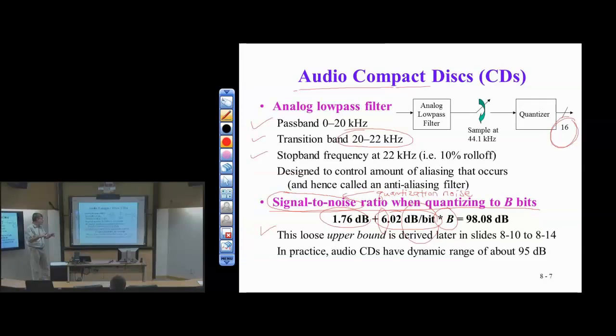Because if we don't, if the quantization noise is less than the thermal noise, the thermal noise will overwhelm the last 2 or 3 bits, whatever it is, of the quantization. They become unreliable, noisy, whatever. If the quantization noise is above the noise floor, then we just introduce noise to our system. But at least it means all of our bits are good in the quantization.